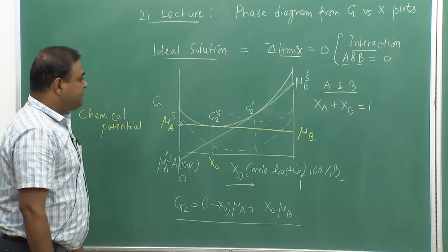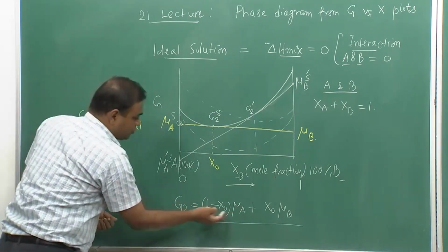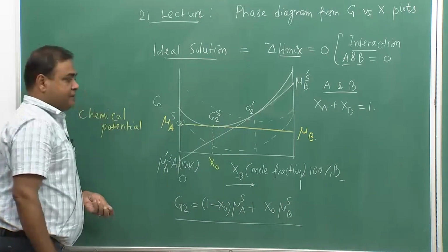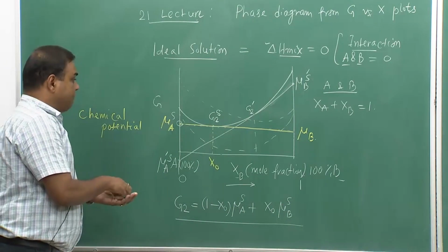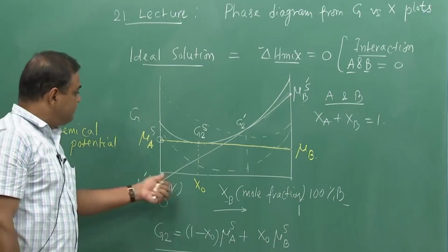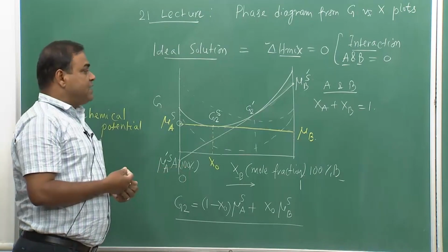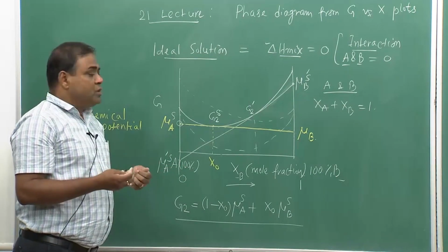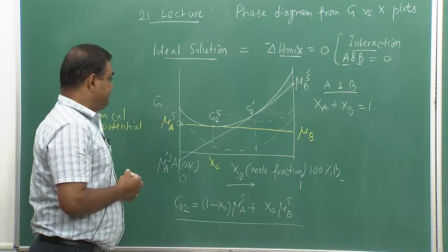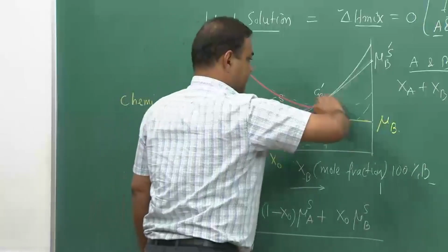Now, if I try to plot just for solid, and that means here also we can make a change, this would be for solid. Similarly, I can have a plot for liquid free energy over this entire composition range, because we are assuming an isomorphous system where liquid-solid solubility would be there from 0% B to 100% B. And here also I can have a graph like this.